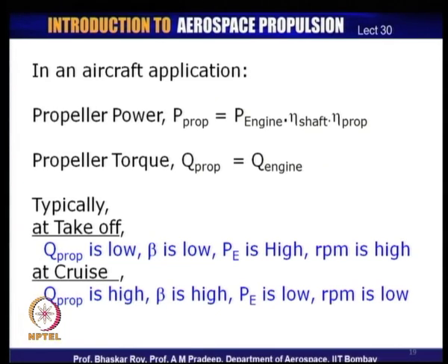So, during cruise and during takeoff, the propellers operate at quite different operating conditions to create thrust, one for takeoff where the thrust requirement is very high, one for cruise where the thrust requirement is rather low, but the torque requirement is on the higher side. So, these are at least two different operating conditions which a propeller has to cater to, to ensure that the aircraft flies properly.